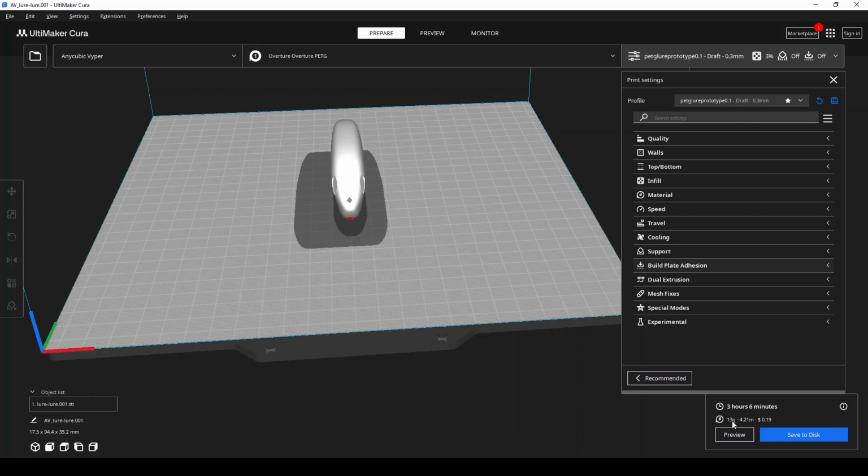Now, this doesn't tell me tenths of a gram. It only tells me whole numbers. So I get 13 grams or 14 grams. And whenever I weigh it, I get somewhere in there. I usually try to fiddle with the infill percentage or something like that until I get it roughly around the next number, so it'll be like right around 12 or 13, so that I know that I'm as close to 13.0 as possible, or 14.0 as possible. But you need to have your filament set up.